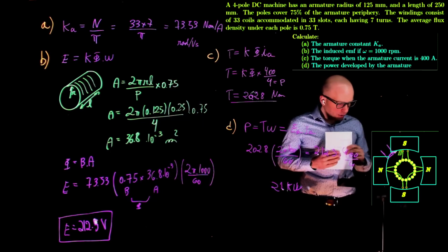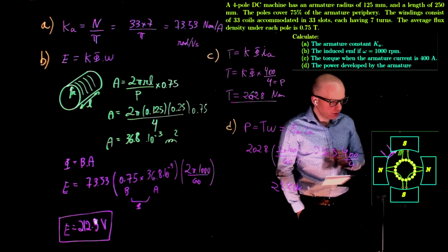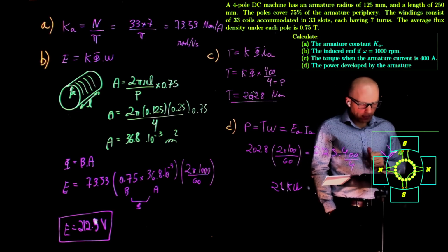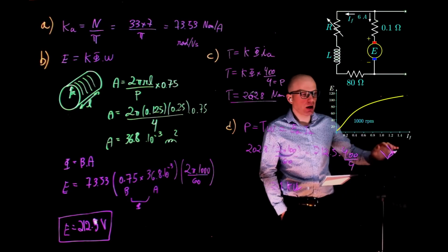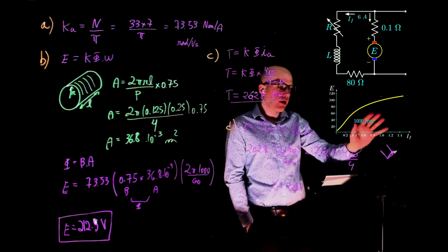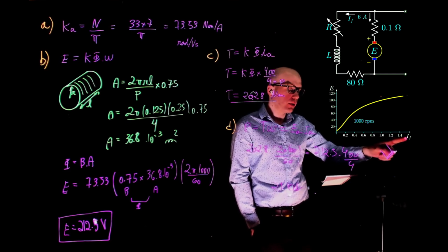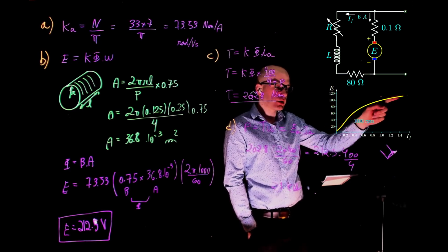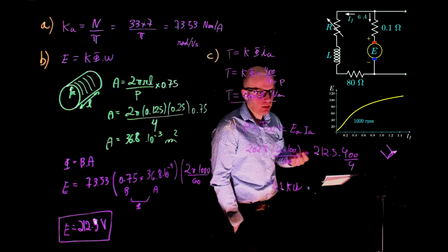In the meantime, let's do lecture exercise 60. We have a DC machine that is connected to a 100 volts DC supply and is operated as a DC shunt motor. At no load, the motor runs at 1000 RPM, and the armature takes 6 amps. A potentiometer R is used to regulate the speed. So we see two important pieces of information here. We have the armature itself, and you have this curve that gives the relation between the applied voltage in the core, the applied current in the core, and the measured EMF as the motor rotates at this speed. So it has a constant speed. As you start to increase the current, the system is originally linear and then it becomes nonlinear, probably because of saturation.